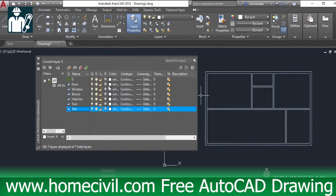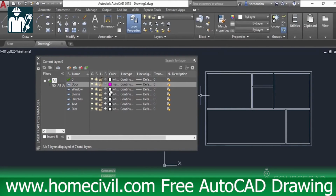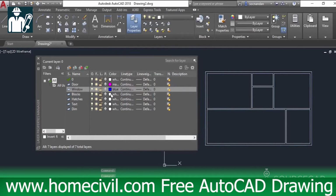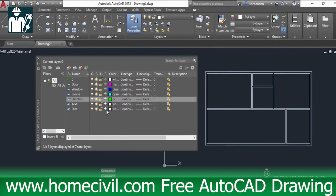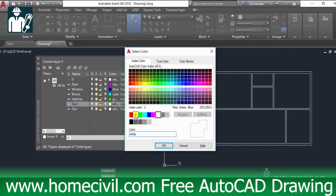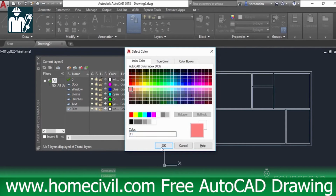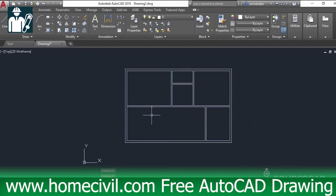So I'll add different colors also. I'll go to this door and add this magenta color to door. I'll go to window. Let's add this blue color. Let's go to blocks, add this cyan. For hatches, I'll select green. For text, let's select yellow. And for dimensions, I'll select this pink color. Alright, so we have added colors, and these colors will be used to differentiate between different objects of the drawing.